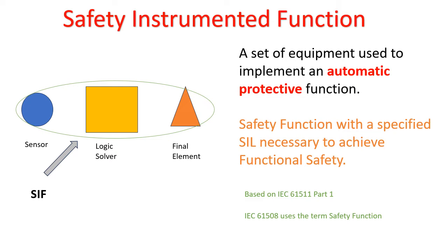So what is a SIF? The full form of SIF is Safety Instrumented Function. As per IEC 61511 Part 1, a safety function with a specified SIL necessary to achieve functional safety is known as a safety instrumented function.